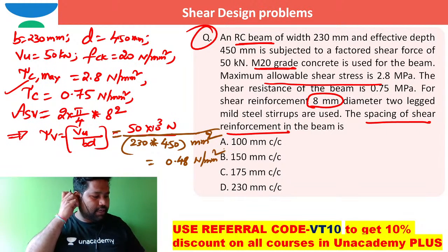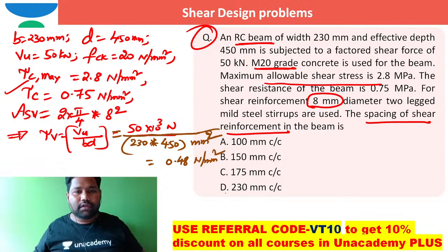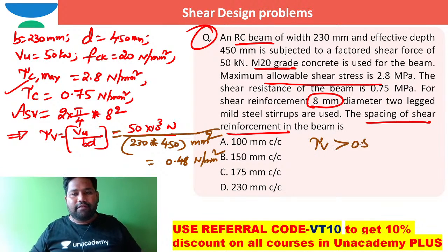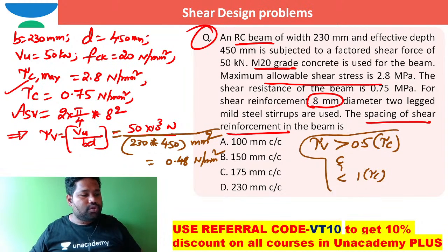Here tau v is more than 0.5 times tau c, and tau v is less than 1 times tau c. This comes under case 2. So here I need to provide minimum shear reinforcement.